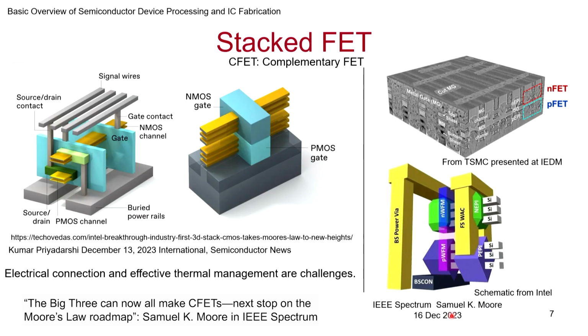So this is what it is. And now this is how it looks, a schematic of it. Now one point I want to bring out: if you look at these silicon pillars or ribbons, in this case ribbons, it's not easy to contact them, and if you contact them, their series resistance can become very high. So they do another trick. They actually grow silicon or silicon germanium around this epitaxially. So originally they have this ribbon structure that I'm showing in the middle of the page. Then on the right side is what it will eventually look like, because these green and blue regions will actually be epitaxially grown.